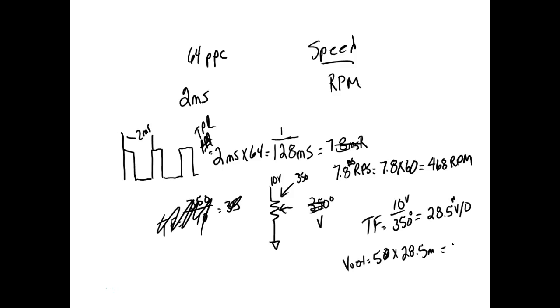You understand? Then normally we have to scale it, right? Y'all know what we mean by scaling. We have to take 1024 and make it mean something. So we might need degrees. Well, I'm getting volts in, but my program needs degrees.